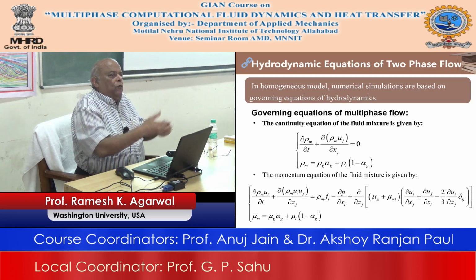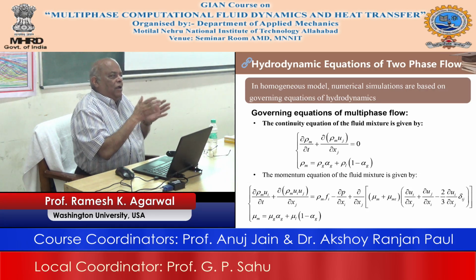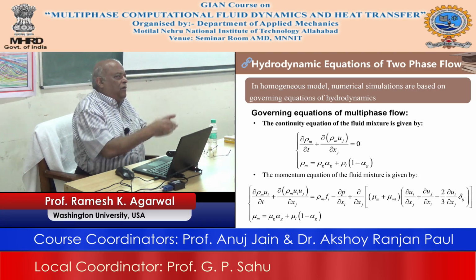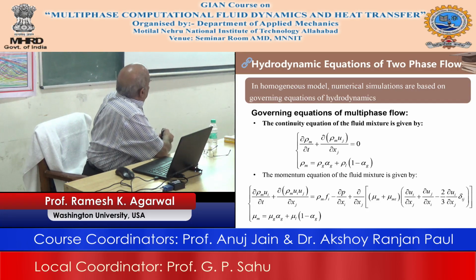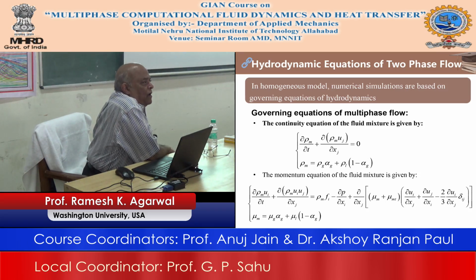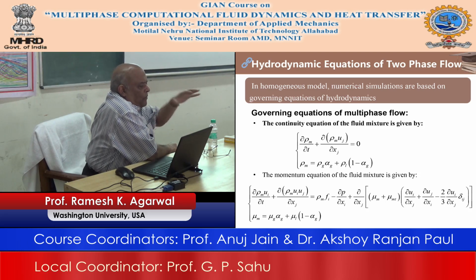Okay. So, you keep on iterating and you will keep on adding to the air pocket until the whole solution is stabilized. It will be an iterative solution of the conservation of mass and conservation of momentum, and now you have to find out this alpha L and alpha G, where alpha L plus alpha G is equal to 1, right. How do you find that out? How do you find out the interface, or the area where air is there and where water is there?